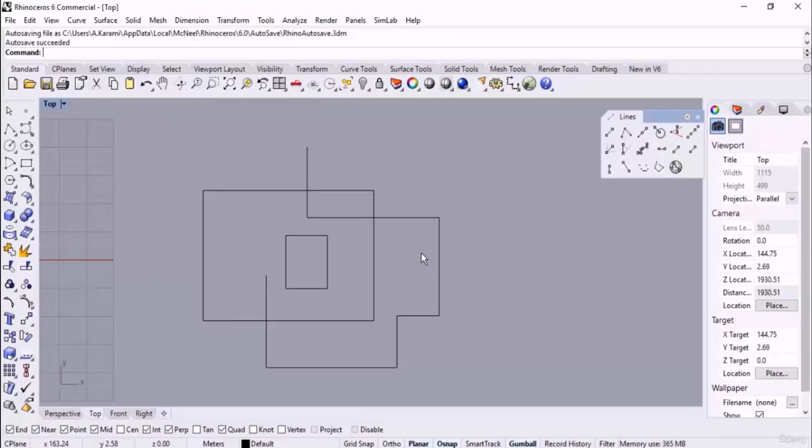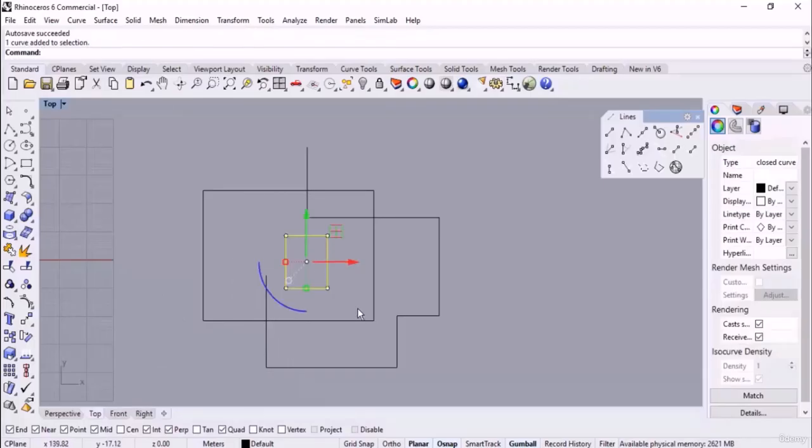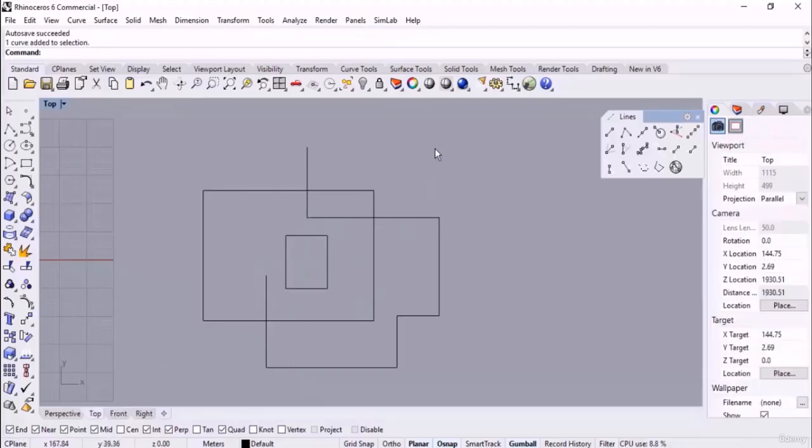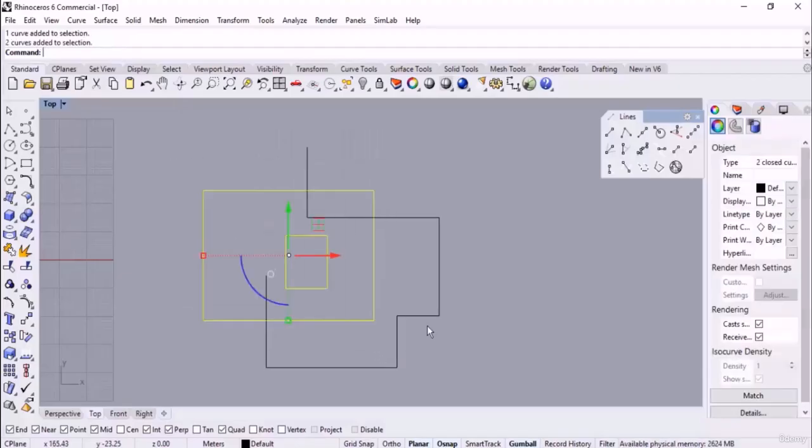Here I'm gonna tell you 3 techniques for selection, which are totally similar to AutoCAD. In the first approach, we sketch a region by click and drag from left to right, but under which condition can we select an object by click and drag from left to right? Excellent. The whole object should be covered in the region, or the window that we sketch should include the object. So in the first approach, we sketch a window by click and drag from left to right.